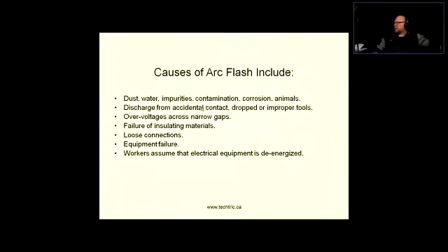All right. Now, what else can cause an arc flash? A discharge from accidental contact, dropped or improper tools. So when you're working around devices like that, tools should be handled quite consciously, and that's the descriptive I'm going to use. Over voltages across narrow gaps.